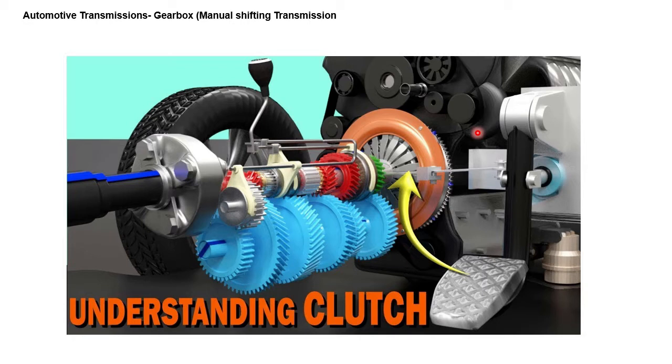If you precisely speak about the gearbox, the ratio is nothing but the speed or RPM of the input shaft divided by the RPM of the output shaft. We understand from the gearbox arrangement that speed is inversely proportional to torque. If the torque is increased, speed is reduced. If the speed is increased, the torque is reduced. The higher gear ratio will have lower output speed with higher torque, and the lower gear ratios give higher output speed with low torque.